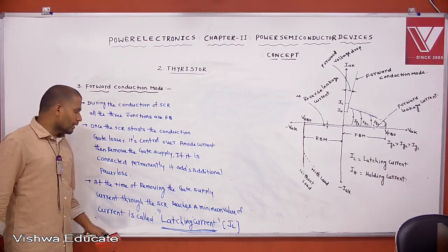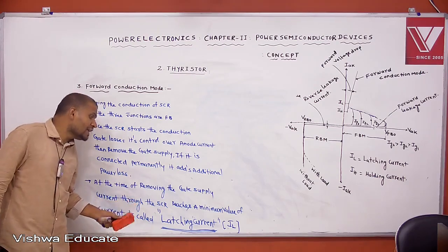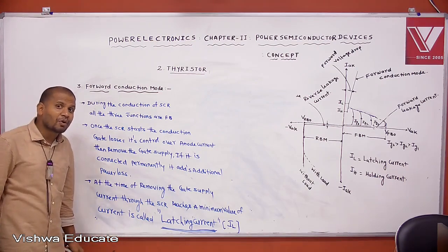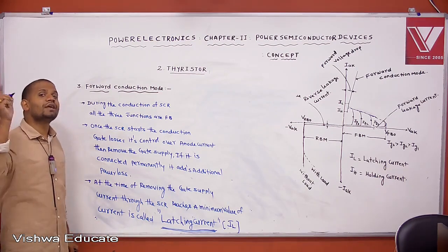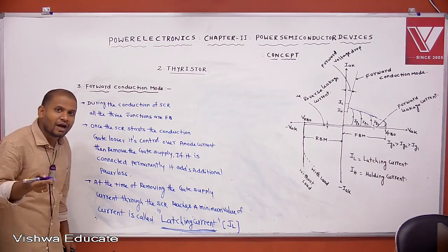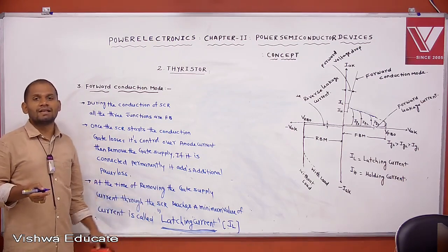Therefore, latching current is associated with the turn on process or turn off process? Yes, it is associated with the turn on process. If you want to turn on the SCR, then the minimum current is latching current.